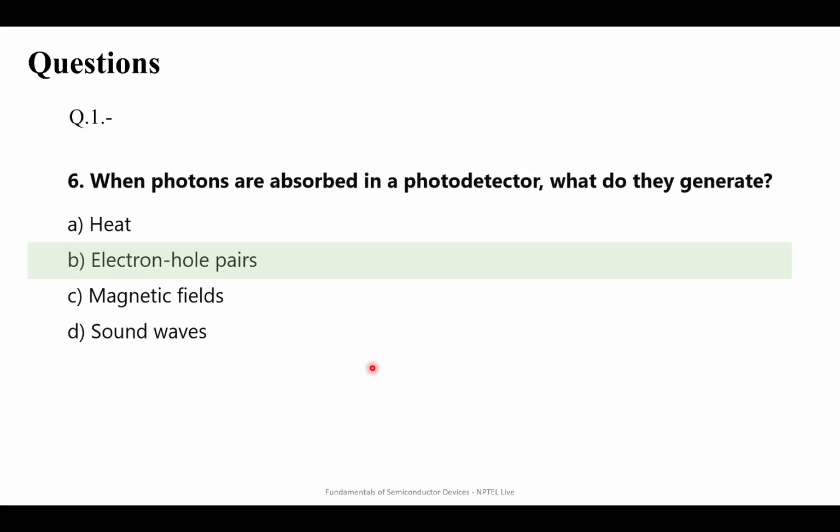So, what happens is that when we shine a light, the valence band will absorb a photon, and this will excite an electron, which will shift from valence band to conduction band. This is called generation of electron hole pairs, as we also learned in last session.